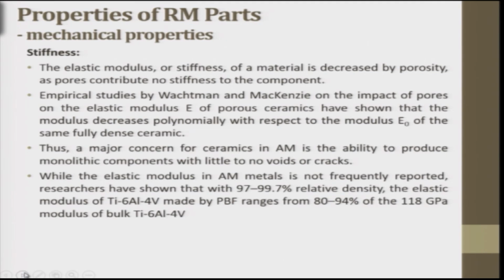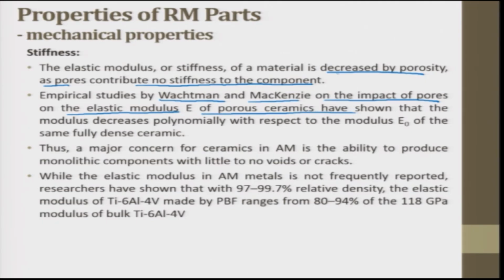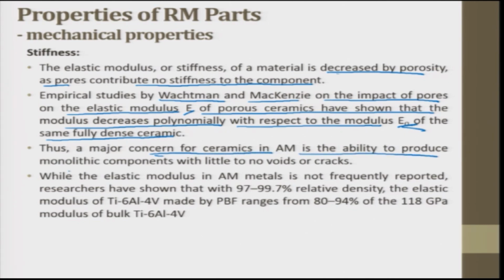Next is stiffness. The elastic modulus or stiffness of a material is decreased by porosity, as pores contribute no stiffness to the component. Empirical studies by Wachtman and MacKenzie on the impact of pores on the elastic modulus of porous ceramics have shown that the modulus decreases polynomially with respect to the modulus of the same fully dense ceramic. Thus, a major concern for ceramics in additive manufacturing is the ability to produce monolithic components with little or no voids or cracks.